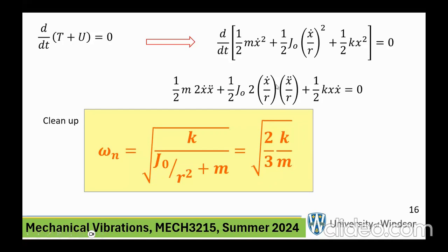Again here, just write it down, use the chain rule: 2 in the front, that thing to the power 2 minus 1, and the derivative of what's in it with respect to time is going to be x double dot divided by r. And this, of course, is going to be 1/2 times, there is a 2 missing here. That's a typo, please note. This is going to be 2x x dot. So there is a typo, a 2 missing here.